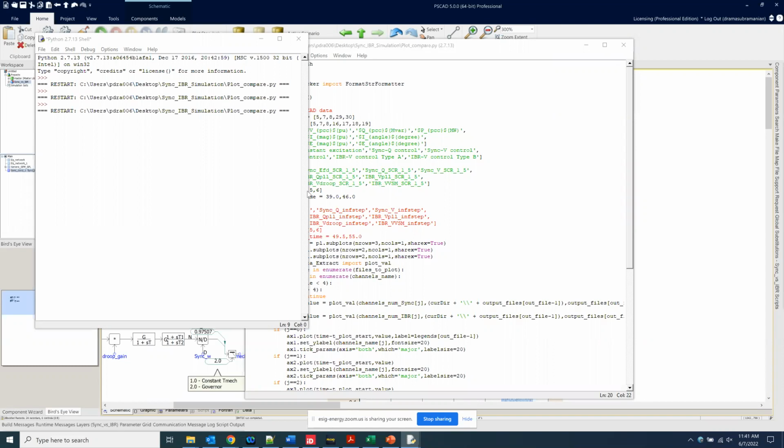One of those types, you still have the capability to operate in what we may call a grid following mode, where you are controlling P and Q. But if you change that to voltage control, and you have another type of grid forming control, which does so implicitly, when you structure the grid forming control loops, and we'll talk about some of them in the next few slides, implicitly in it, there is a way of voltage control embedded into that control. So if we look at it from the perspective that what the inverter is actually doing is shifting from being Q control to V control, that can be one pathway in which to start bringing in grid forming behavior